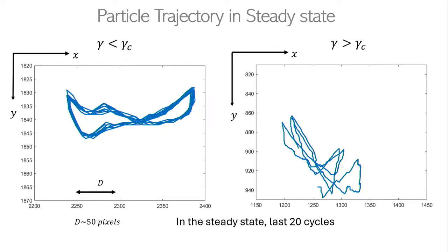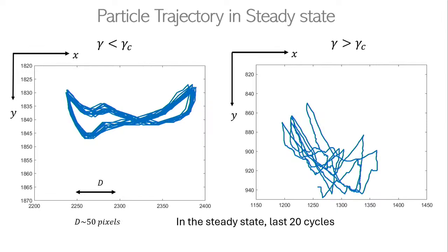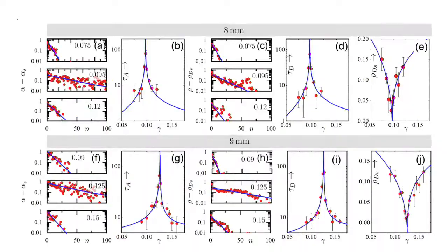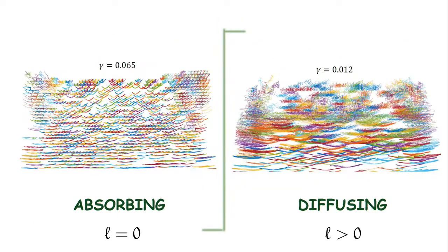You're wanting the one for which there's a very rapid loading of the system. Because I guess the shape has to do with the position of the particle. Yeah, maybe I can give you a quick answer to this. Here it is. You look at these particles, this is over the entire thing, and I have not plotted all of them, only some, it's been very crowded. These ones are less loopy, the holes are less. This is moving the maximum, because that's the bottom plate which is moving, so the loop is extended up here. The ones at the boundaries are more loopy. This is also because these are rotating particles. All these particles are mainly rotating, and anything which rotates gives you more loopy kind of structures.